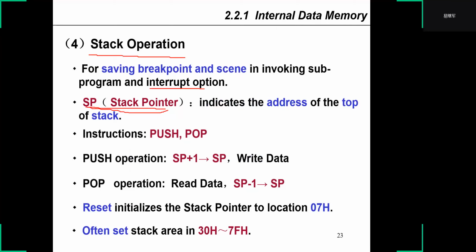So the SP always indicates the address of the top of the stack. When we want to save something in the stack, we use the instruction push. Push adds 1 to SP, then writes data to the stack.